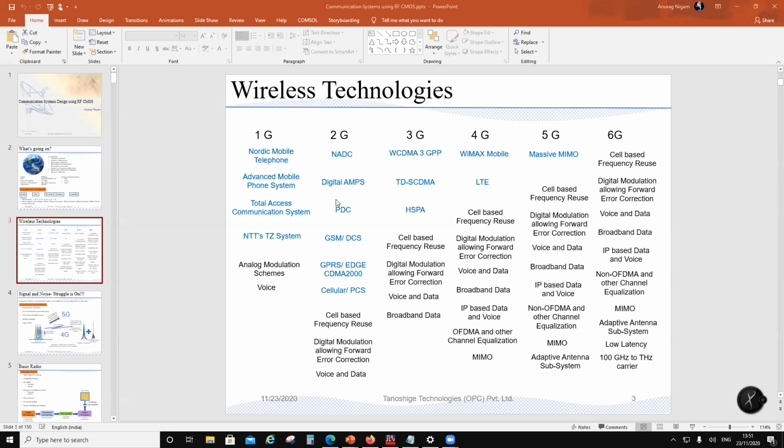Okay, so a particular subscriber is allotted a particular slot in a particular channel frequency for transmitting, and a particular slot in a particular channel frequency for receiving. Okay, so that will be called time division multiple access, right? Then there are CDMA technologies. Now in CDMA, what happens is, instead of using a carrier frequency, I would be generating a PN sequence. Okay, now what is unique about PN sequences?